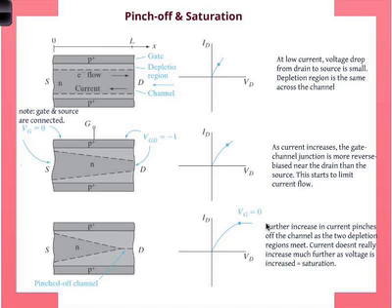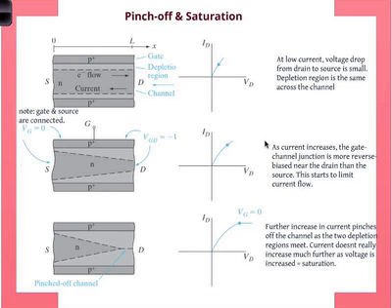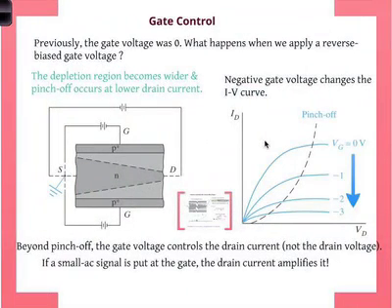So of course, how does this work as an amplifier? It works as an amplifier because you can have different families of curves by changing the gate voltage. This is one specific gate voltage, and you get one current-voltage curve. You change the gate voltage, you get a different current-voltage curve, which is what's shown here. So you have a family of curves, one for each gate voltage.